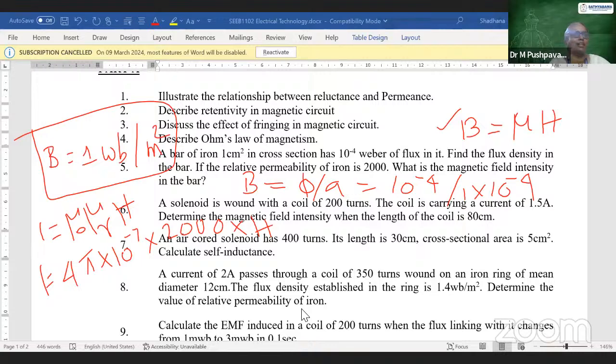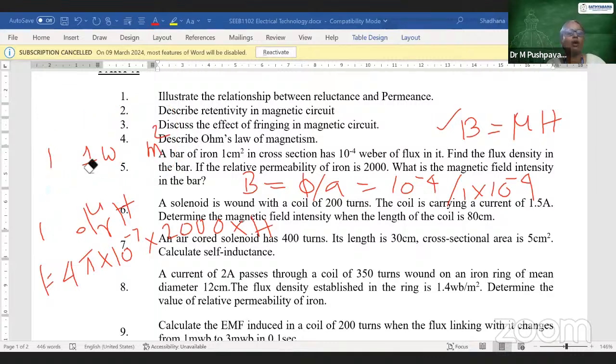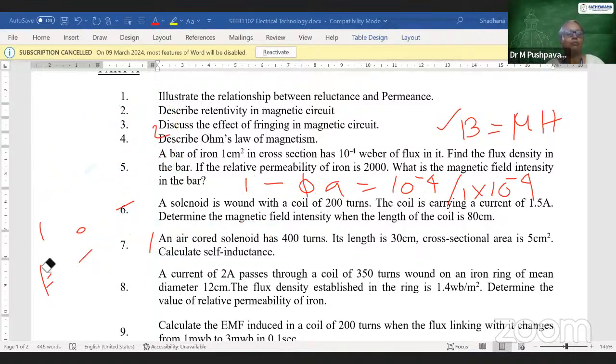398.08, that's not a problem. The fractional value got a difference now; it's not a problem. So 398.0308 ampere turns per meter. That is the correct answer. Okay, so this is a one part B, probably important. Then do the sixth problem.